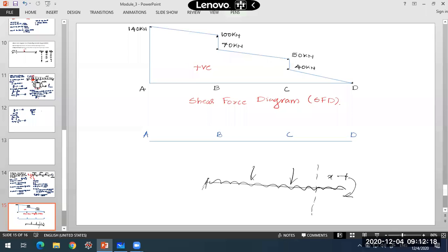I told you in cantilever beams it is better to move from the free end to the fixed end. So you have this load intensity W. At any distance, when I calculate the bending moment, it will be expressed, in this portion between C and D, as W into x by 2.